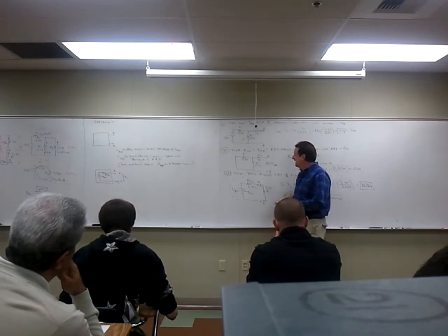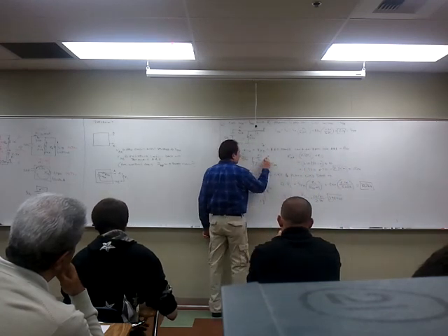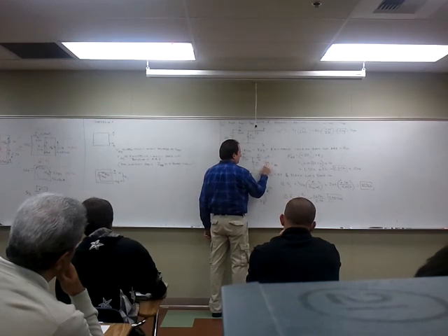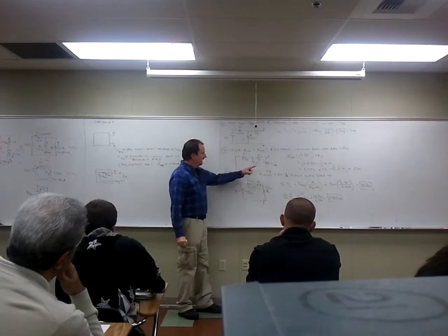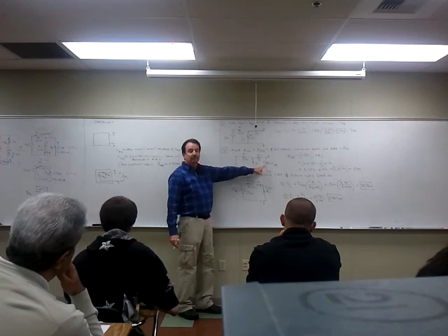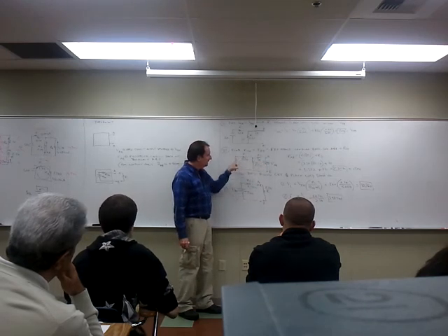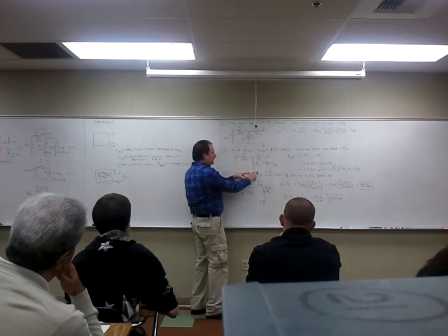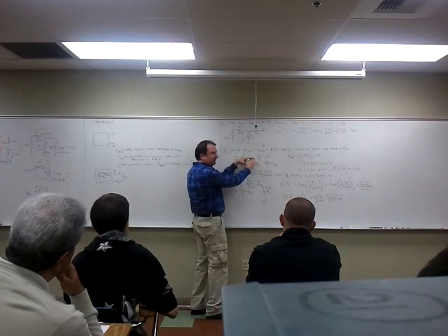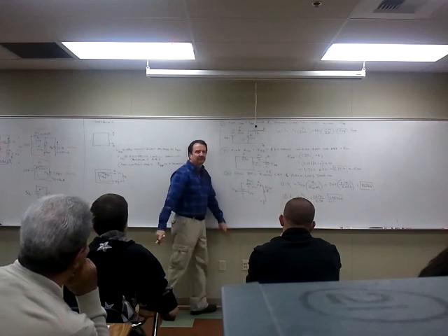So if I put a battery out here on the output, and I found R total as if this was the circuit, that would be R Thevenin. In other words, what does this battery see as a load? Doesn't current leave and split among these two, so these two are in parallel. Then all flows through R3, which is in series.